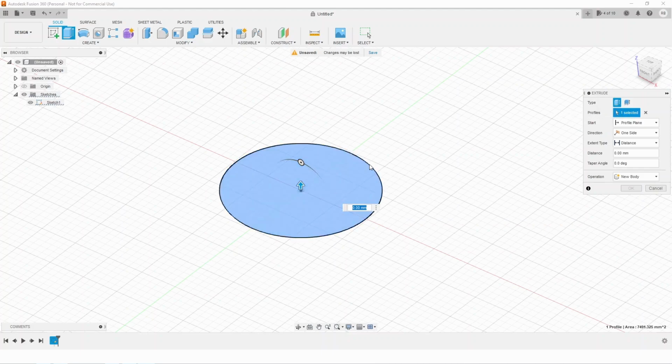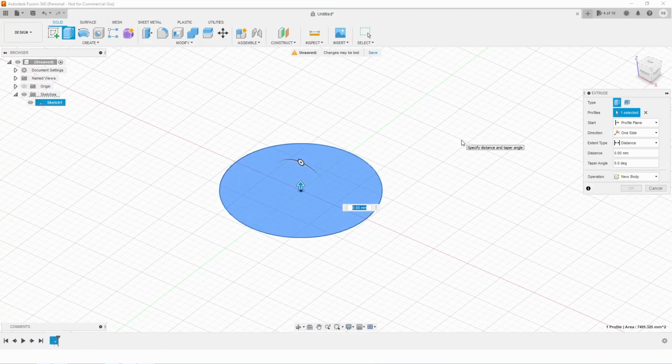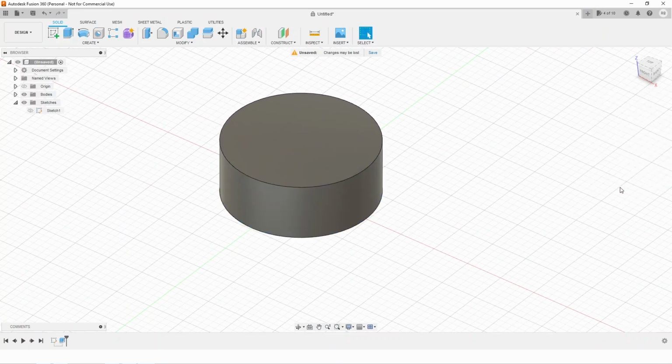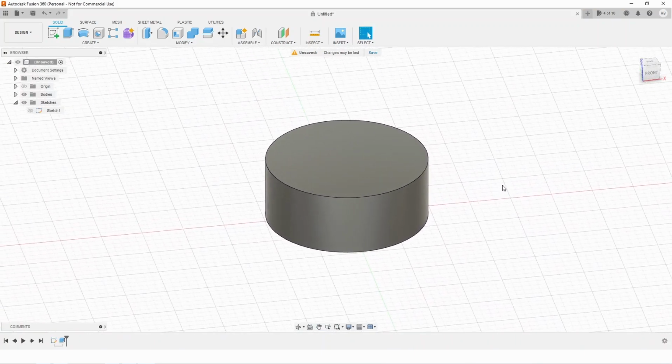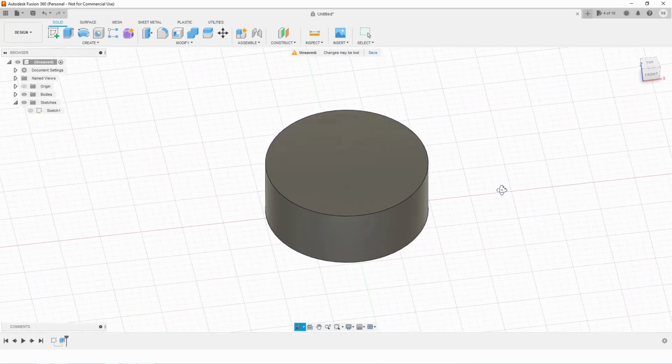If we wanted to deselect this one and do it manually, we can press this little X button, and then you see this default select. It's asking for what shape should we extrude. So I can hover over my circle and press it again. Now I'm gonna drag out the shape and make my amazing 3D cylinder, like so. And this will be your first CAD model ever. It's not very beautiful, but it's a start.